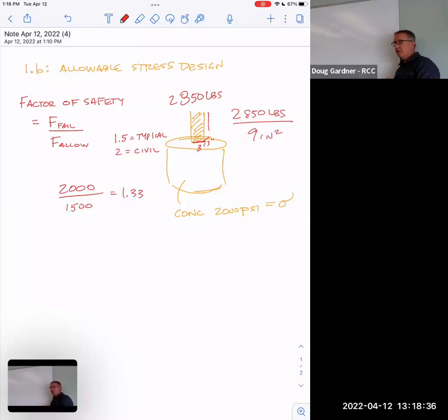So they have hundreds of these test cylinders, and they wait 30 days and then they break them all to make sure that they actually have the PSI, that job spec. And if they don't, the bridge is already hard. It's been 30 days. They got to go jackhammer it all out of there and start over. So it's not something you can afford to screw up. But that stuff has to get tested. Just because it says it on the bag doesn't mean it actually happened. So it's a pretty interesting process.